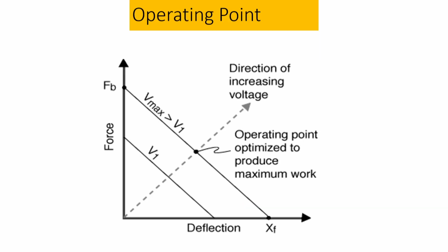Now, one important thing I want to tell you here is that there is always a particular operating point at which we need to actually use these sensors or actuators. Why? Because imagine you have a piezoelectric material. Now, imagine that I am applying a voltage across it, and this voltage is going to create a change in the system, and this is when it is completely free. So, it is somewhere here, it shows a large deflection. Now, imagine that I am not allowing it, I am putting some walls that stop it from expanding, but it wants to expand. So, it is going to create a force. So, this is the blocking force.